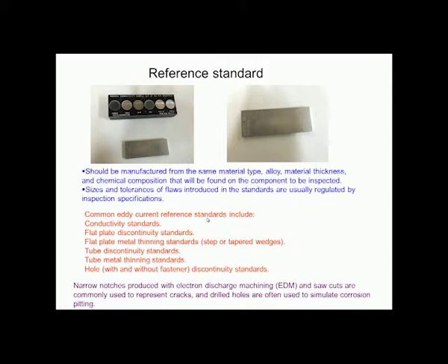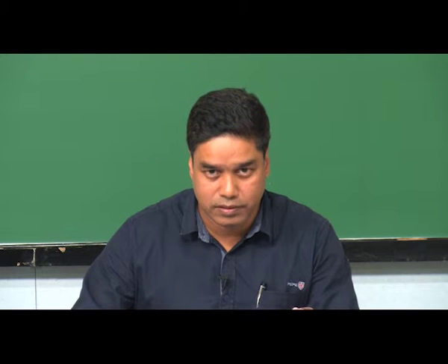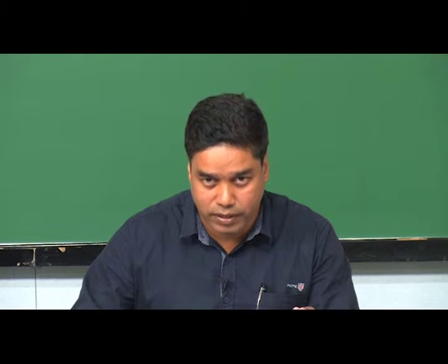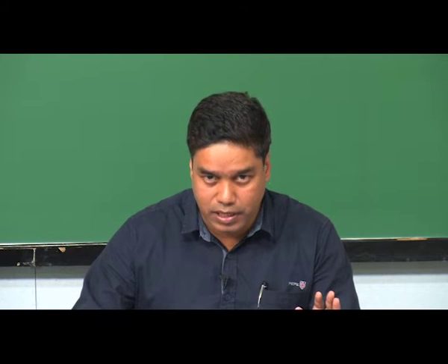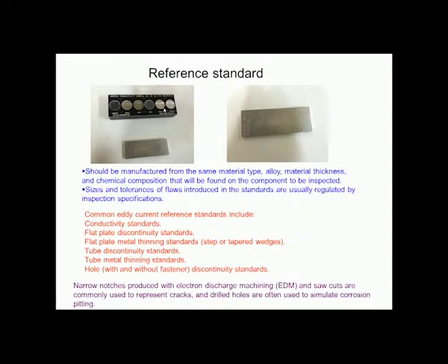And these are the commonly used eddy current reference standards, which include the conductivity standard, which is this one. These blocks are of known conductivity and they have different conductivities. So, using these blocks of different conductivities, you would be able to calibrate the instrument for the electrical conductivity. Then you have flat plate discontinuity standards, and one of them we have seen in the video, which is this one.